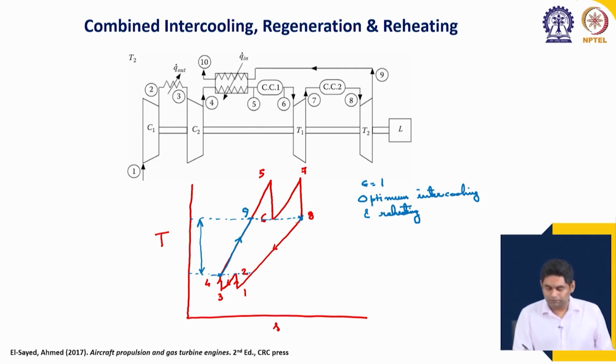The corresponding heat transfer will occur from state 8 and we will reach temperature equal to T2. Let us call this state 10. So, from 8 to 10 is the heat transfer in the regenerator from the combustion products. Then from 10 to 1 we have the additional heat removal process to the external low temperature reservoir, which is the hypothetical process we added for closing the loop, as we have already discussed several times.